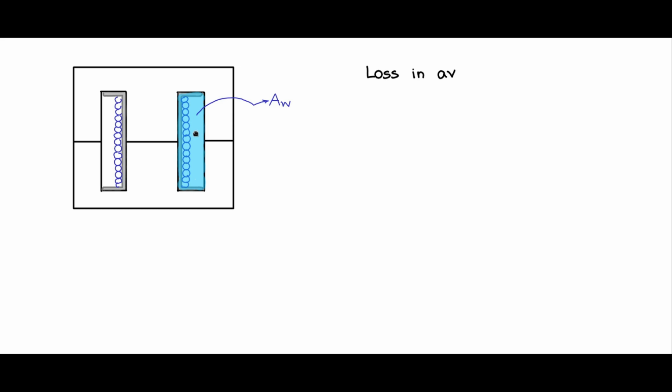However, you should understand that the entire window area is not available for you to fill up with windings. So there is some loss in the available window area. What is the loss? One is we just saw that there is this coil former which is eating away a portion of the area. Then when you are winding, the cross section of the copper wire is circular in nature, and there will be air gaps in between the windings.